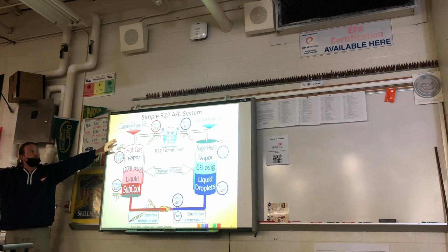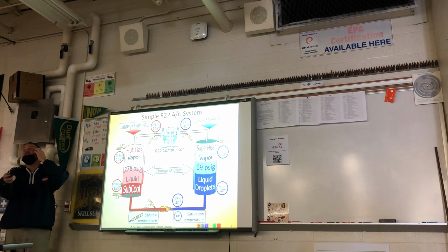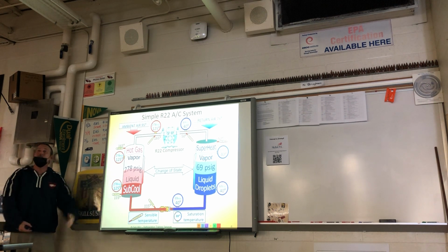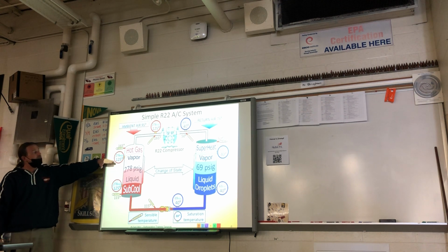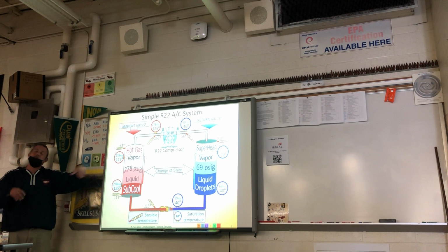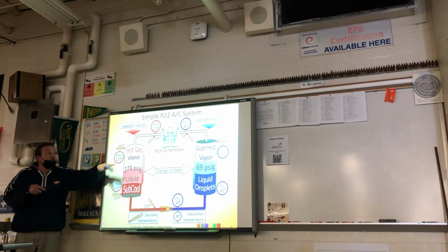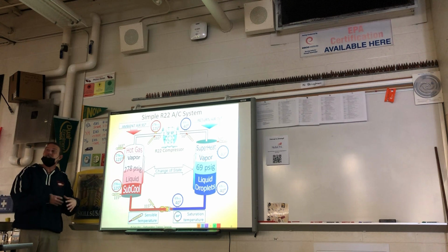134A. That's right. This one's green. That one is blue. Yep, no, pink is 410, and with 410, all these numbers would be higher. And that was the fear for 410, because the 125-degree temperature you needed with the 410 brought this pressure up to 400 psi, 450. And that means that we're dealing with twice as much pressure. They needed to make bigger hoses. They needed to make bigger, thicker compressors, all right? Because they thought that this stuff was going to explode and be dangerous.